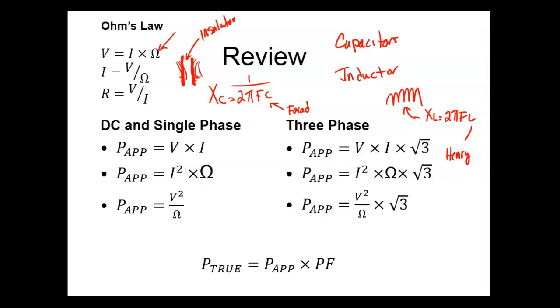So what happens is that if we put AC in a circuit that has inductors or capacitors, it creates phase shifts between the voltage and the current in the circuit. ELI says E is for voltage, by the way, so we know that E is another term. So in an inductive circuit, voltage leads current. In a capacitive circuit, current leads voltage. So they're opposite of each other.